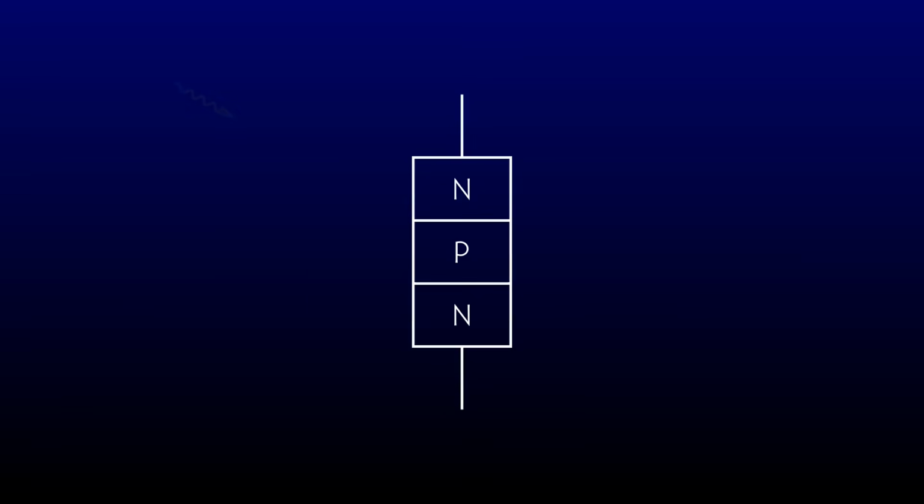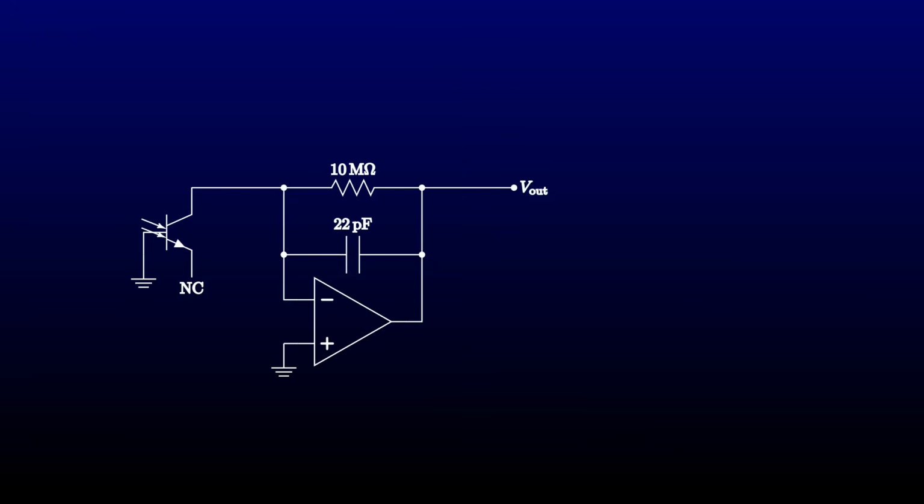Just like a photodiode, a phototransistor works by having a photon deposit energy near a junction. The energy can shake loose an electron, leaving an electron-hole pair. This time, when the carriers migrate, the hole is migrating to the base emitter junction. That amounts to a conventional current between base and emitter. Transistors still have current gain, so we'll see a much larger current between collector and emitter. A phototransistor therefore outputs a much larger current than a photodiode.